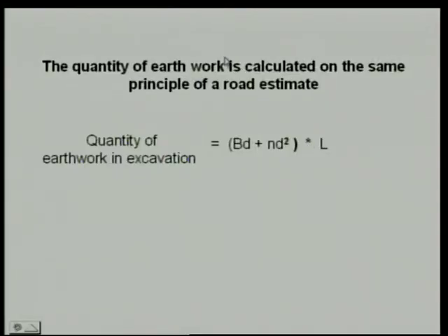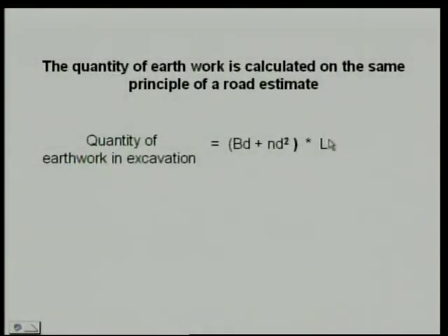The quantity of earthwork is calculated on the same principle as a road estimate. That is, just now we have seen how to calculate the earthwork for a cross section of a road both in cutting and in banking. Similarly, the cross section of a canal is also a trapezium. So, the quantity of earthwork in excavation is nothing but the sectional area multiplied by the length.